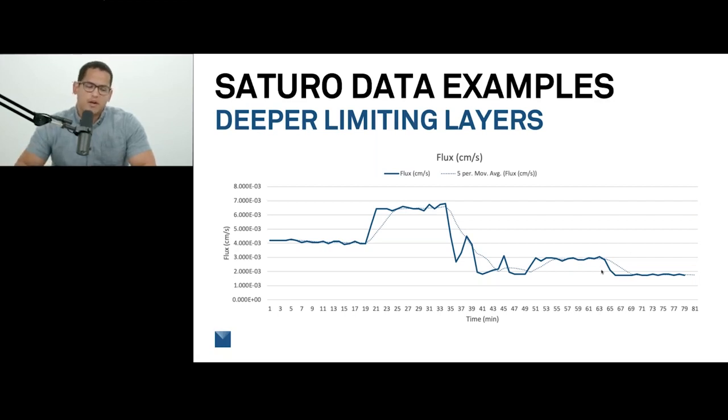through the profile. At the end of the day, hydraulic conductivity is going to be limited by the most limiting layer. So if we're trying to understand the max capacity, this is really the part that we need to understand. But understanding these early components is also important in understanding, earlier in the season when the soil is drier, how much water can the soil infiltrate, versus as it gets wetter during wetter seasons, what's that actual value going to be? These all play really important roles in our understanding of soil hydraulic properties.